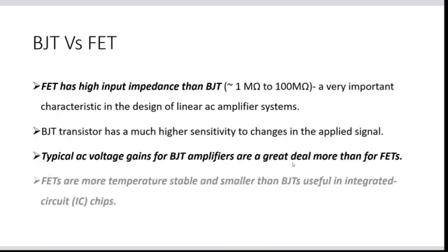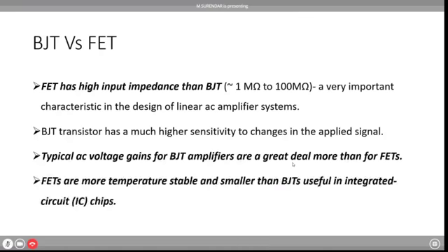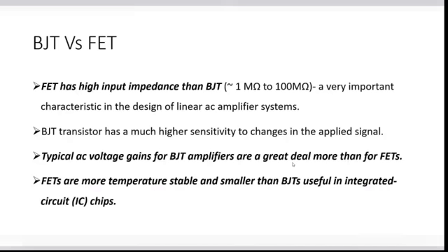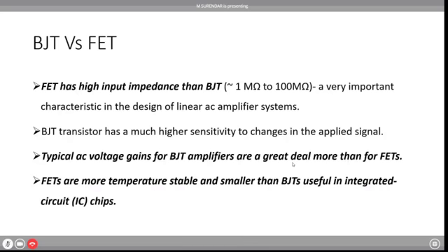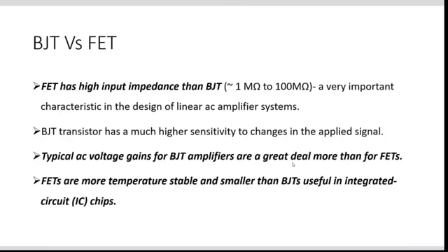And FET is more temperature stable, whereas BJT is not highly stable with temperature, because in the BJT we have the problem of thermal runaway. This thermal runaway is because of the collector current. We have already seen that; you already had a 1 mark or 2 mark question in your CT1.